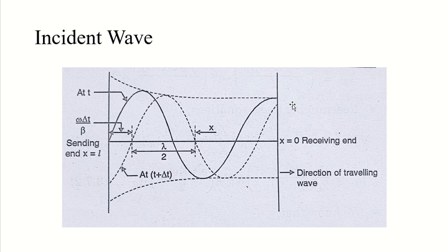So now, let's call the distance x, as we are taking here. The distance x from the receiving end will increase the first term in the equation. What was the first term in the equation? It was root 2 (Vr plus Ir Zc) divided by 2 and e raised to alpha x dot e raised to j(omega t plus beta x). This term will also increase in amplitude. Okay, it will not normally increase, it will increase exponentially, and it will advance in phase.